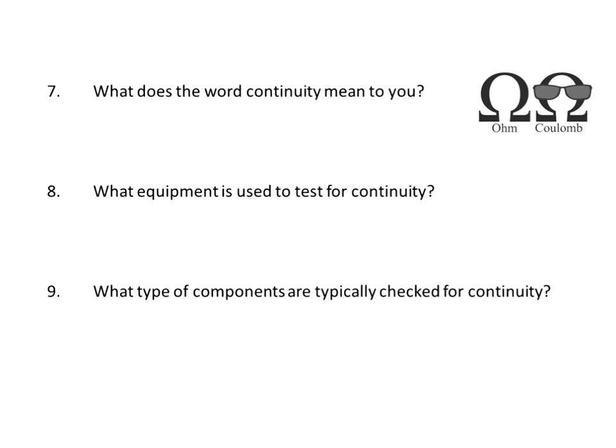Okay, what does the word continuity mean to you? Part of this class is learning about the different words that older engineers will use out in the field. And perhaps you didn't hear the word continuity too much when you were at PTI. Well, continuity means that there is a circuit connection, a conductor between the 2 points that you're testing. It's called continuity. And that actually means there's a short between those 2 points.